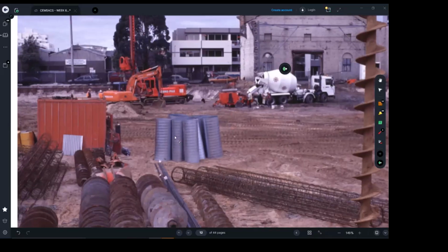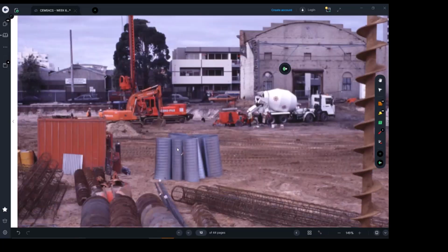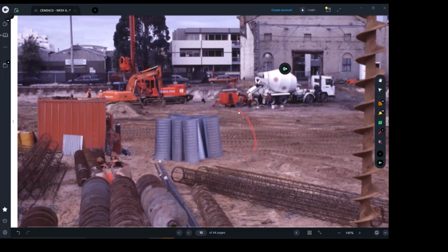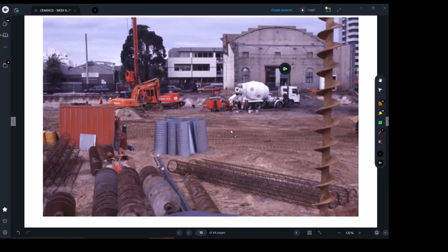Say you have 10 meter deep bored piers, and typically we may have some disturbed soil at the top, maybe the first meter or meter and a half, that is very unstable. While you dig the first meter, you can hammer down or place those shoring components just to help temporarily prop that soil.